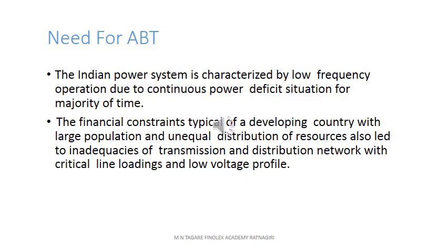You can easily understand this by taking a simple example of a generator. Let us say a 5 megawatt generator is supposed to run at 1500 rpm, so that it generates 50 hertz frequency power. Now, if the alternator is supplied with some mechanical power, it will start generating.